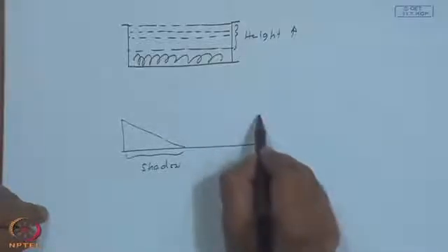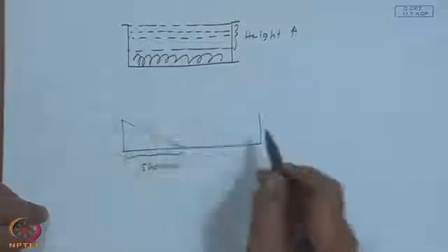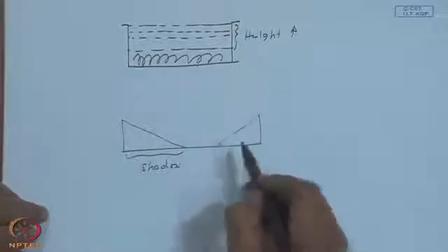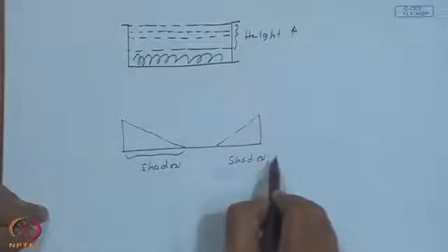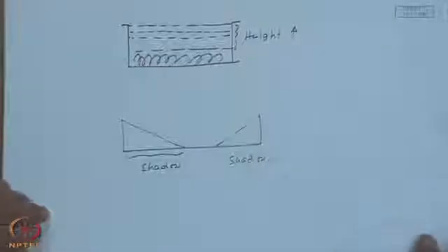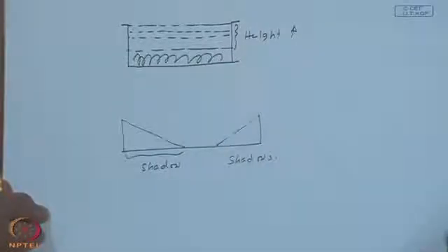So, morning sometime to the left, let us say, and afternoon sometime to the right, there will be shadows because of the box height. Then maybe 10%, 20% of the absorber will be ineffective. So, this is one consequence one has to face by continuously increasing the number of glass covers, thereby increasing the height of the collector.